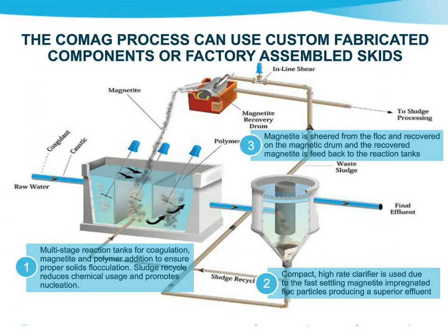Either a small circular clarifier with a sludge rake or rectangular clarifiers with plate packs or tube settling media can be used as a solids separating device. Between 15 to 25% of the sludge from the bottom of the clarifier is recirculated back to the ballast tank. An additional 2 to 5% of the sludge is fed to a shear mill, where the magnetite is separated from the sludge and then recovered on a rotating drum. As mentioned before, the waste sludge minus the magnetite is sent to a sludge dewatering device.